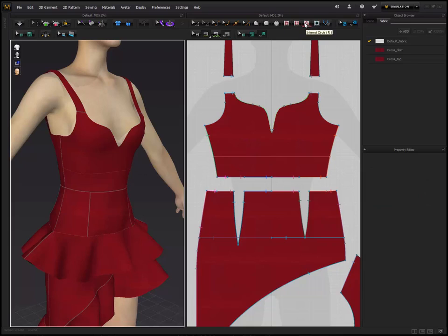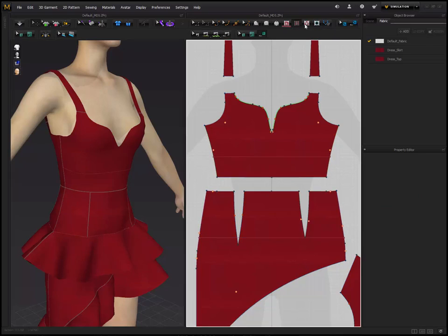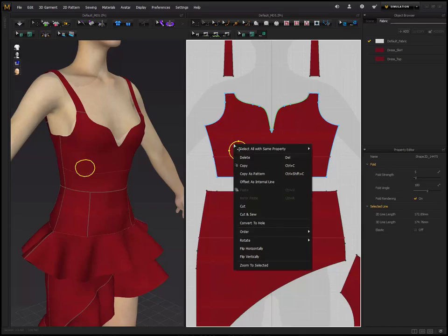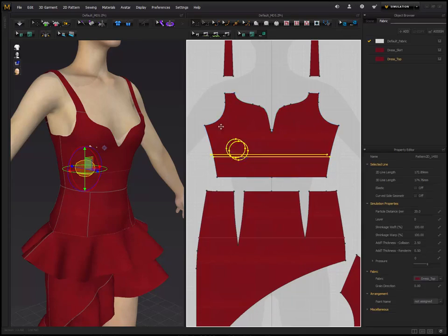Besides using a dart, you could use the internal line. So a circle or the square or draw it out. If you use the circle option, you could put a hole in the mesh by creating it, double clicking it, and you could right click on this and you could cut. This will add a cut into the mesh.